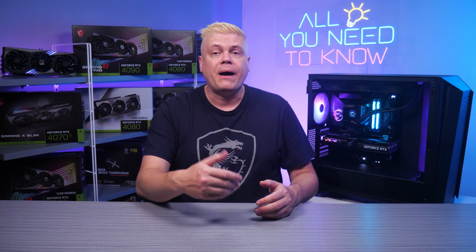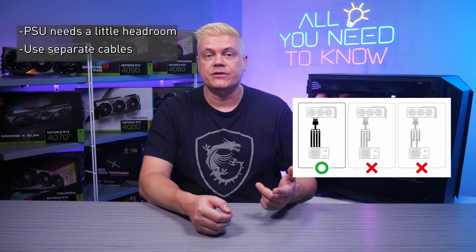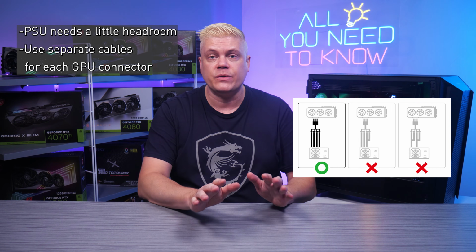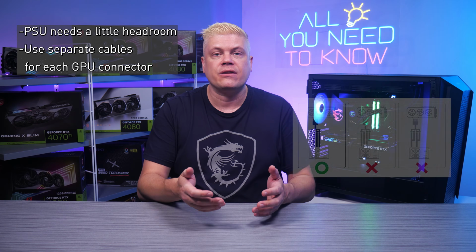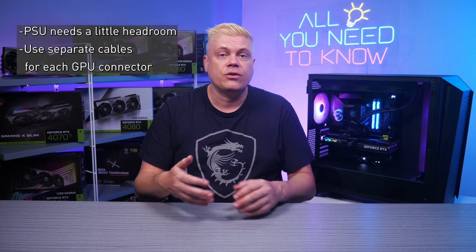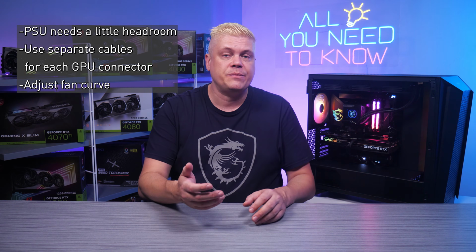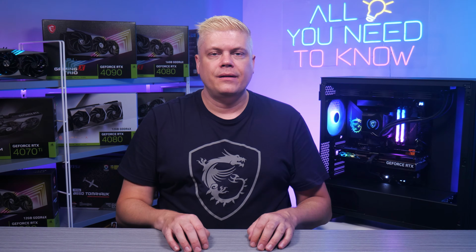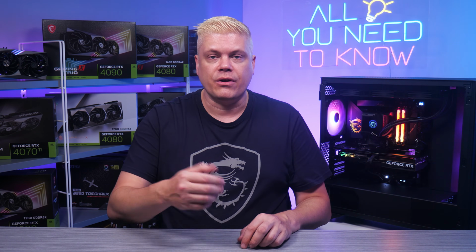Some notes. Your power supply will draw more to handle the overclock. You need to use separate cables from your power supply to each connector on your GPU, so you can't connect with the first one and also use the pigtail. This is because transient spikes can trigger the overprotection of your PSU, and maybe not right away, but over time, turn off your PC when it spikes. You'll need to adjust your fan curve as your GPU is using more power, producing more heat, and we'll cover that later.